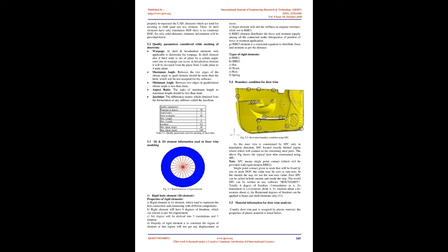He has done research on FEA of an automotive door trim panel made of lignocellulose composites in order to determine the stresses and displacements in case of a door slam simulation. In his research, a new lignocellulose composite made of polymers reinforced with woven fabrics of natural fibers and wood particles was created. The mechanical properties of these materials were determined experimentally and used as input data in FEM simulations. The finite element method result emphasized that the new material improves component stiffness compared with classical materials used.